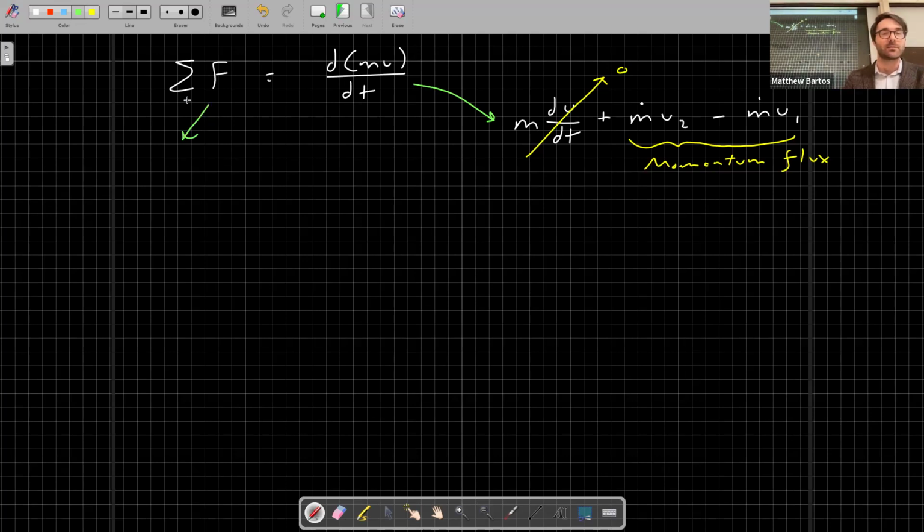All right, the sum of forces, as we talked about earlier, is going to be rho times g times the centroidal depth at the upstream end times the cross-sectional area at the upstream end, minus rho times g times the centroidal depth at the downstream end times the cross-sectional area at the downstream end. We can also express this mass flow rate in terms of other variables that we might know.